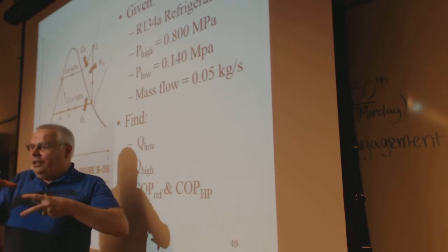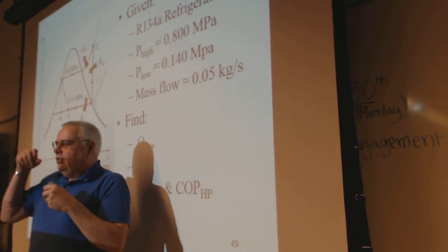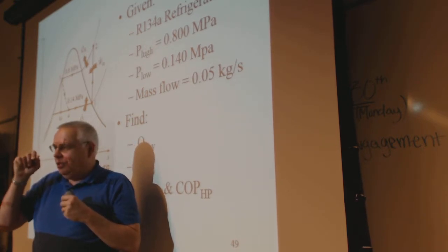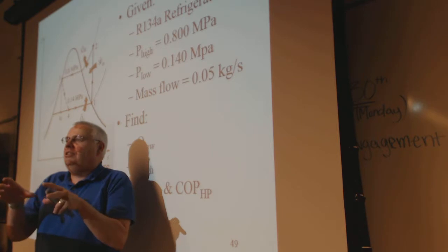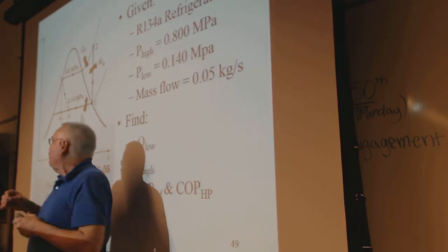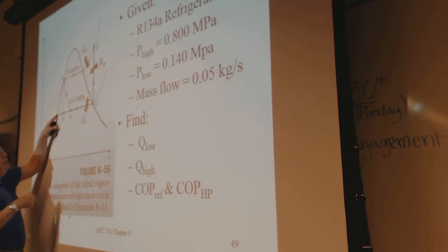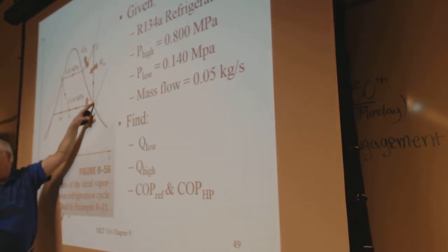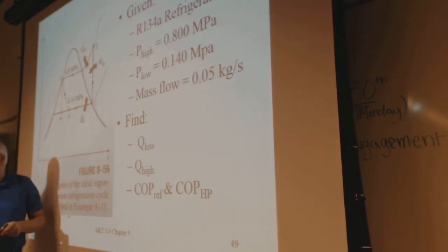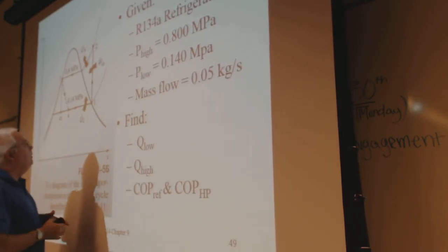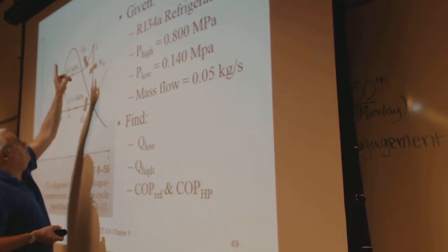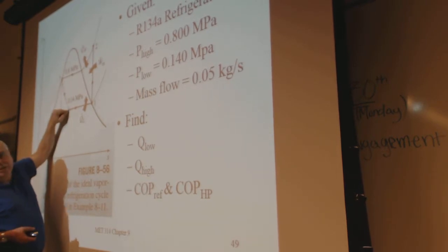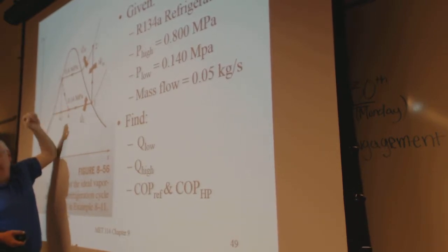We don't add work. It's insulated, so when it drops, it sprays into the zone. It starts out as liquid at high pressure, maybe high temperature, and by the time it's done spraying into the low pressure zone, it's evaporated into a fog. And that's what, over here would be liquid. This is fog getting thinner and thinner until finally it's saturated vapor, not a fog, it's clear. Fog is little droplets that have condensed. So isentropic, constant pressure, and then same enthalpy is kind of the new and different thing there.